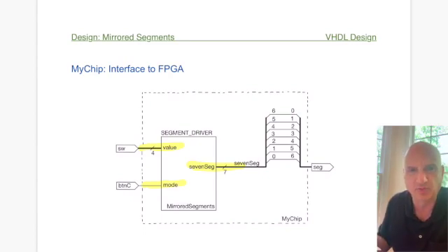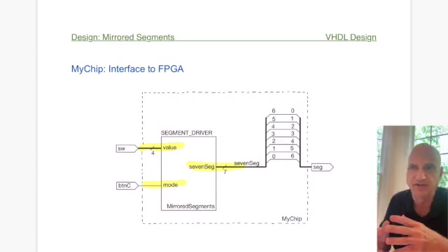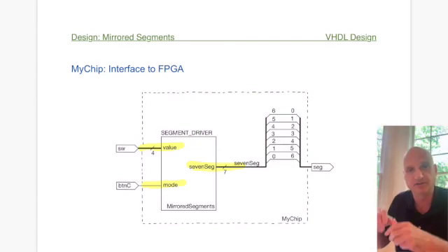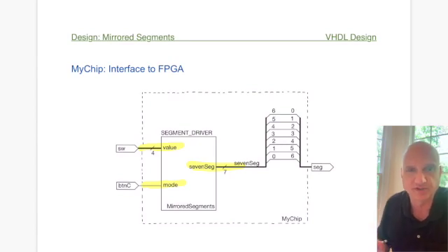In our particular board, this is targeting the Basys3 board from Digilent. Like I said, the board's irrelevant. All that matters is that your design interfaces properly to the switches, LEDs, and other resources that you want to use. All of these resources are tied to specific pins on whatever board you're targeting, and you have to map those pins to the actual ports in your design. To do that, there's a configuration file. In our very first VHDL project, we went through the whole process of opening a configuration file and uncommenting the areas we're going to use, such as switches and LEDs. You'll want to do the same thing here: uncomment the configuration file and make that a part of the overall design.